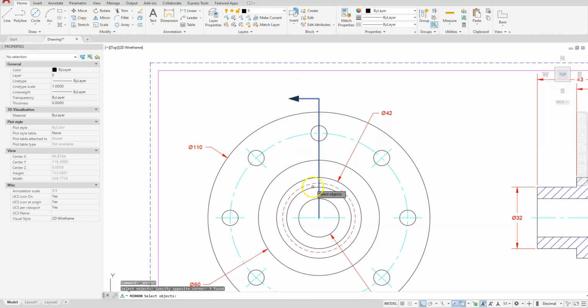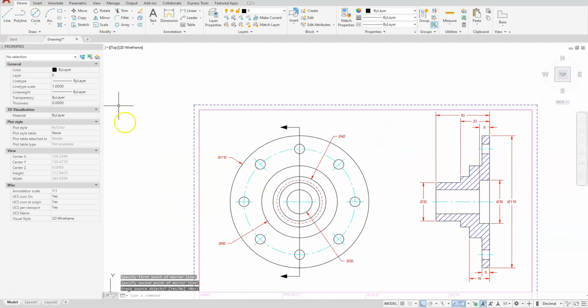I hit the enter button a little too quick, and it does happen to me from time to time. So let me go to endpoint, and then answer that question by hitting enter. I want to join 3 lines together, and do not join your arrowhead. So when I use the join command, I only want to join this line, this one, and this one.